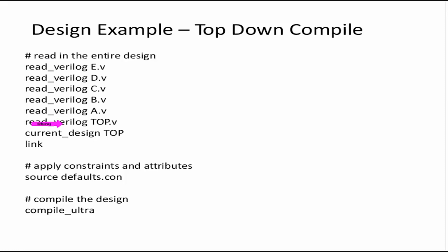That's the recommendation, because the analyze and elaborate combination will give much more insight into the design exploration, right? So you can view all the warnings easily and so on. It sets the current design to top and performs a link command. Now what does the link command do? This command